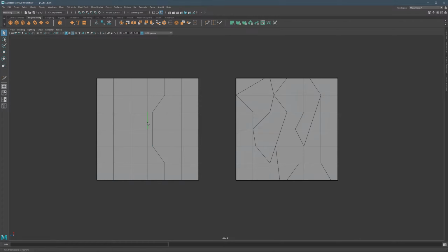And let's now also talk about adding details and, like I said, easily manipulated geometry. Say, for example, I want to add a detail here that has this look. The thing is, now I have a polygon here that is fairly large and one here that is fairly small. So what we can do is even that spacing a bit. This is something we're always going to try to watch out for: evening out the spaces and making sure that the specific edge flow continues.